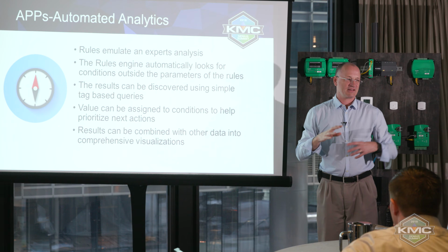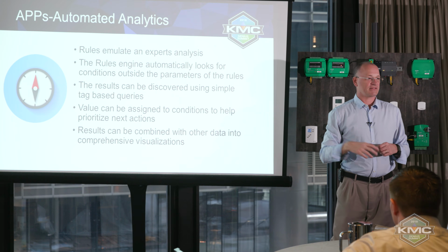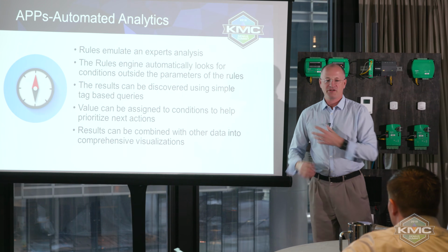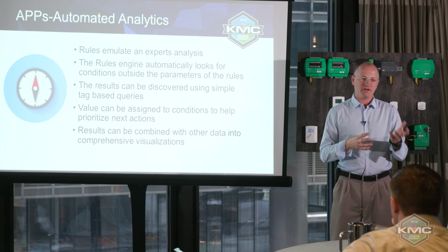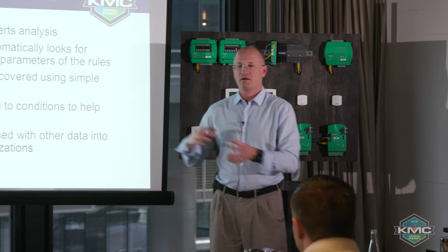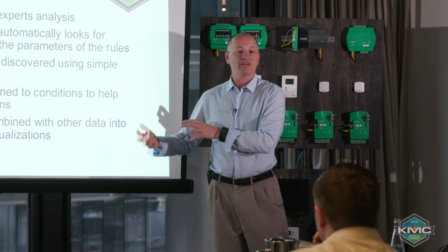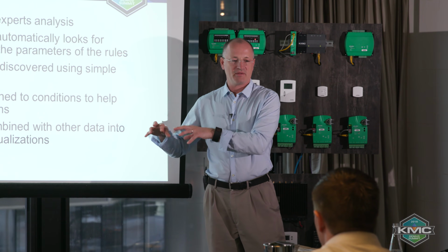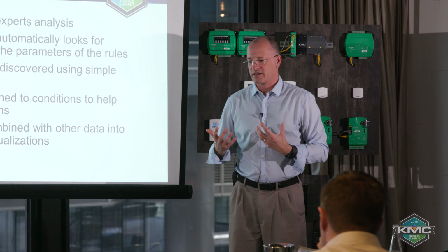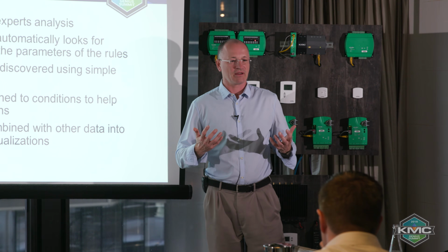How many of you know what analytics is? Okay. In my simplified version of it, it's kind of what we already do today with real-time data inside a control engine, but it's more appropriately looking at historical data in a rules engine and then putting together the conditions that I'm looking for. So a classic example would be simultaneous heating and cooling.